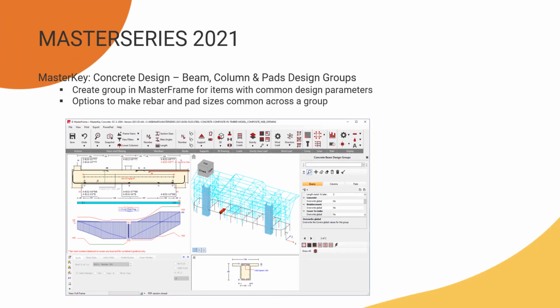Okay, another really nice new feature that's been on the list for a while, and great to see it realized in MasterSeries 2021, is the inclusion of design groups for concrete beams, columns, and pads. Really nice feature, allows you to group these entities together so that some of their design properties are different from the otherwise global default properties. You can adjust all sorts of things for these members on a group-by-group basis, as well as providing rationality in the provision of the reinforcement by saying things like all the reinforcement in a beam set is the same for the main rebar or the shear links.